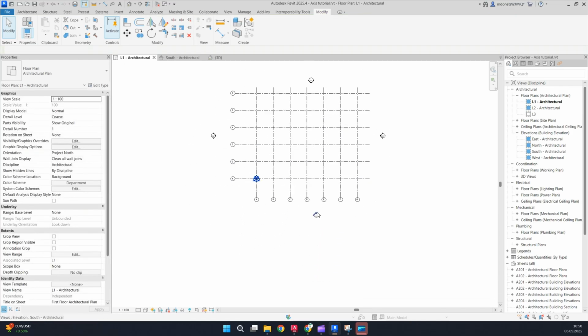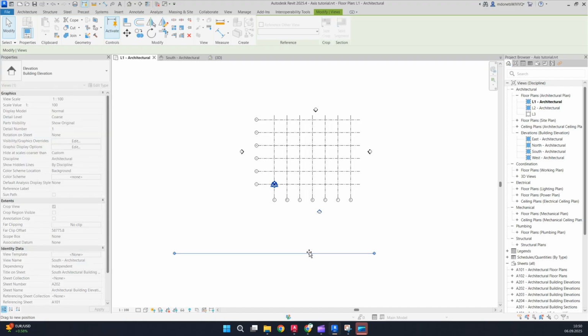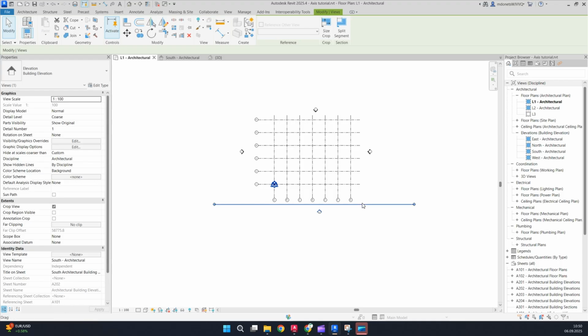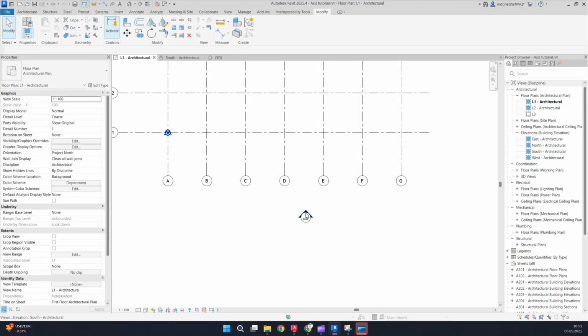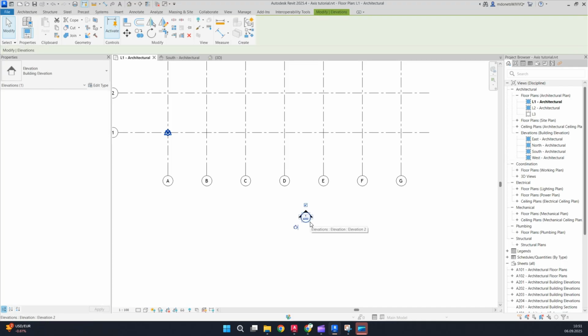And now let's check our elevations and move the elevation plane somewhere closer to our building. This blue line is the elevation plane, and everything in front of it will be shown in our elevations. Now we're good to go. Let's go with double clicking this elevation, or just picking it straight away from one of our views in the project browser. I will click twice here.